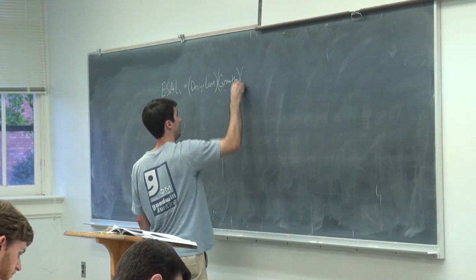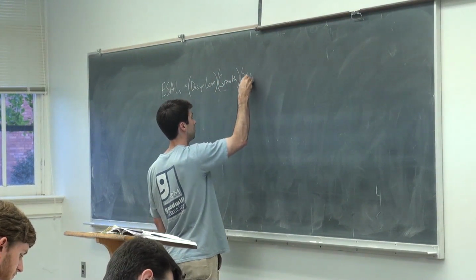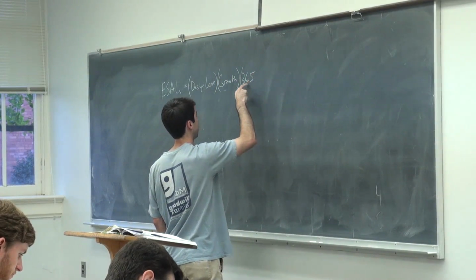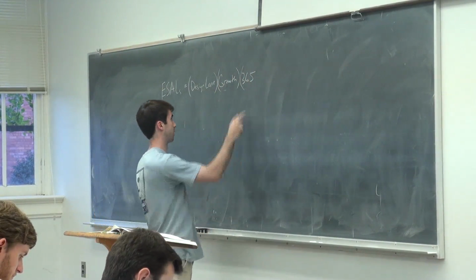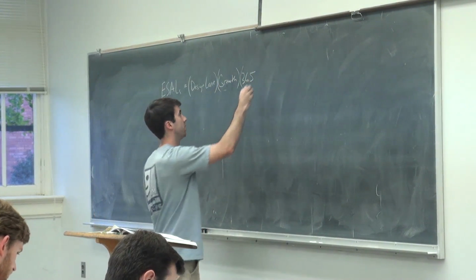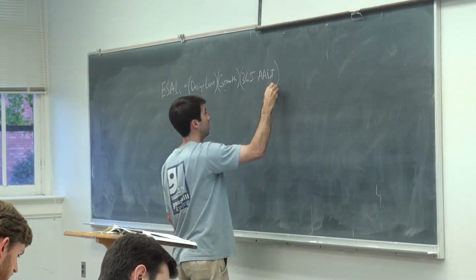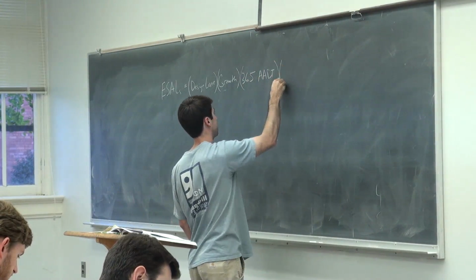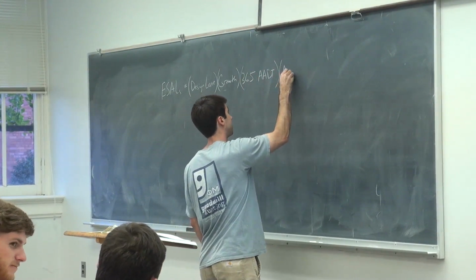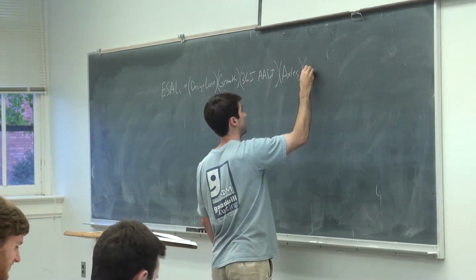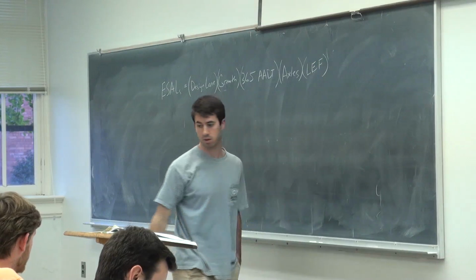growth. You've got the daily traffic, but it's annual, so you want to do it... sorry, it's the average annual, but it's daily traffic. We want to look at this over 20 years, one year at a time. So we say 365 times the AADT, and then times the number of axles, times the load equivalency factor.